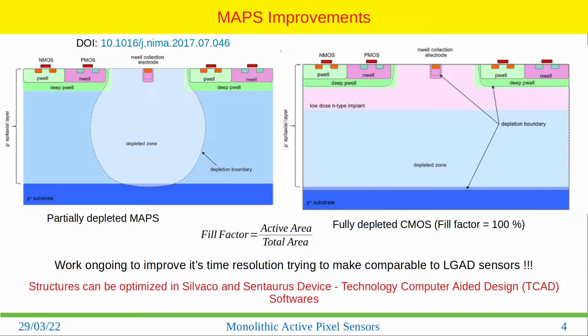This particular structure I already explained. We have a lower density p-type layer which we call the substrate, and then we create the n-type doping, and then n plus, to improve the ohmic contact. Then this structure will create a bell shaped depletion region, and then we have the PMOS and NMOS transistors here. And this deep p-well, as I mentioned, confines the charge in this region. It will not allow charge to enter because of the large barrier.